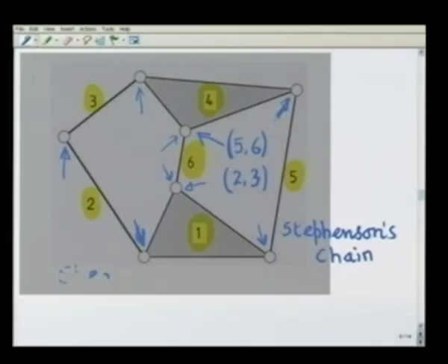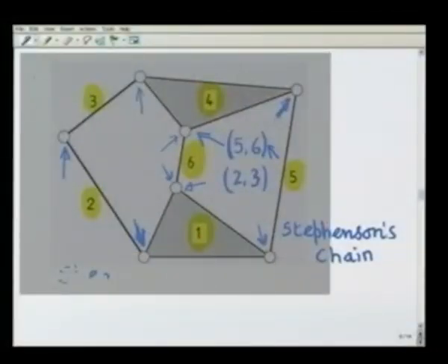So by kinematic inversion, we can get three different types of Stephenson's mechanism, depending on whether the ternary link 1 or 4 is held fixed, or one of the binary links in this group, that is either 5 or 6, is held fixed, or one of this group, namely 2 and 3, that is either 2 or 3, is held fixed. So there are three possible different types of Stephenson's mechanism which can be obtained by kinematic inversion from the same Stephenson's chain. We will now see a model of a Stephenson's chain to generate a Stephenson's linkage where a ternary link is held fixed.